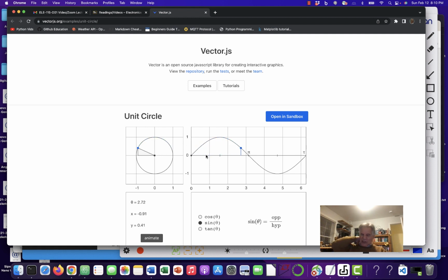So very typically, we will talk about sine waves with phases, okay? And you'll see it as we go along, but just remember that this is a true sine wave. It has 0 degree phase. A sine wave that has, say, 60 degrees phase would be written as sine of theta minus 60 degrees in the parentheses, okay? Because mathematically you'd have to start it off late.